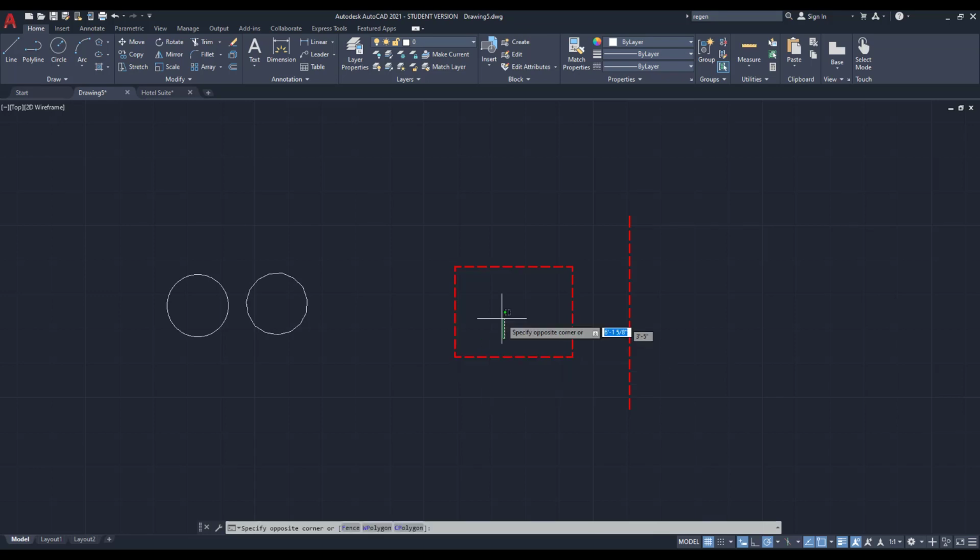So actually let's start with the shortcut command, okay? So SC enter, scale, and then it is saying to select the object. So I'm going to pick the object, and it is looking for a base point. So, for example, I want this rectangle to become bigger from this point. Okay, so you see, I'm making it bigger or smaller, and this is my base point. Okay. And yeah, so you can go ahead and insert a scale factor.